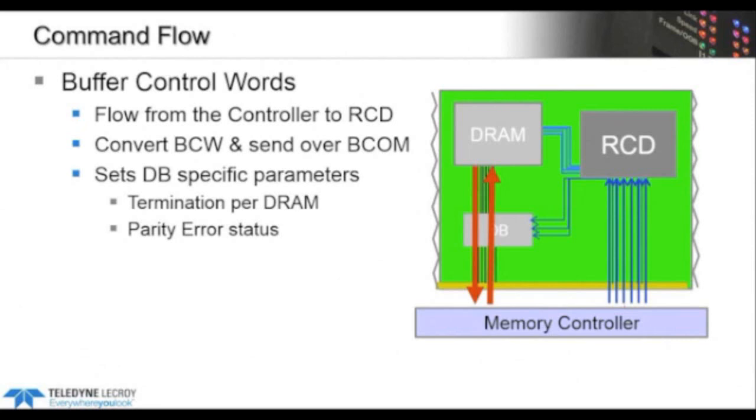They're highly configurable. Again, they allow you to customize every aspect of the termination, the signal strength on the DQ lines, in both directions. There are commands to optimize power consumption on the data buffer. There are read-write delays that can be added per data line. So no doubt, a lot of controls. The RCD carries some of this load, but it's mostly on the host controller to get this working. So having an analyzer to get visibility to the host commands is pretty key, both to just get the system configured as well as reaching the higher speeds that DDR4 is promising.